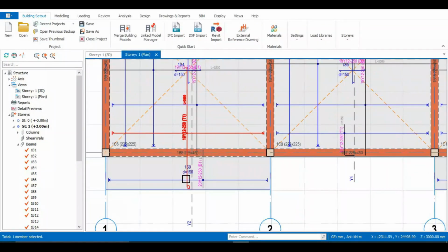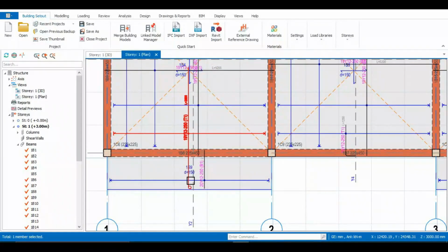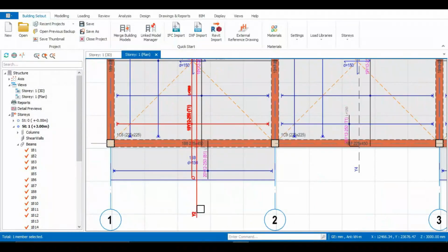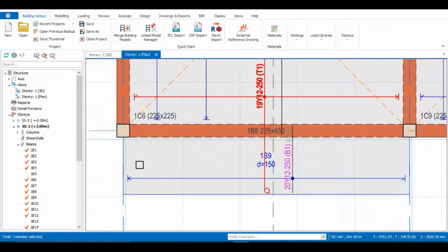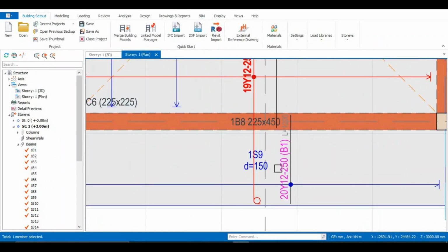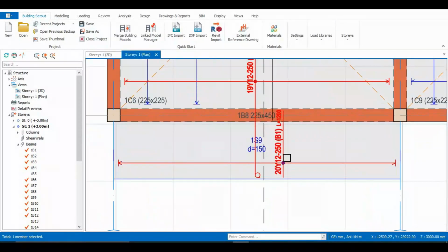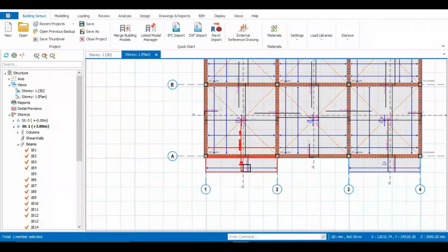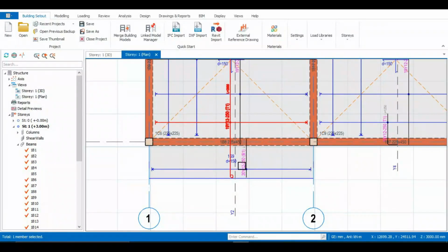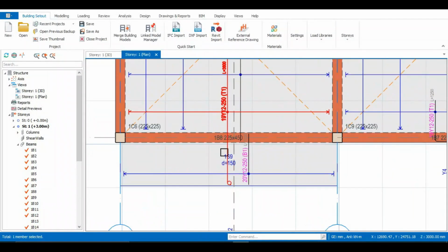But nonetheless we have that reinforcement on the y-axis. We need the reinforcement on the x-axis. So this is going to be our bottom one. We need a bottom two that we'll be using, and we also need a distribution bar on top of it. And if we are going to do that, we'll use our manual strips.